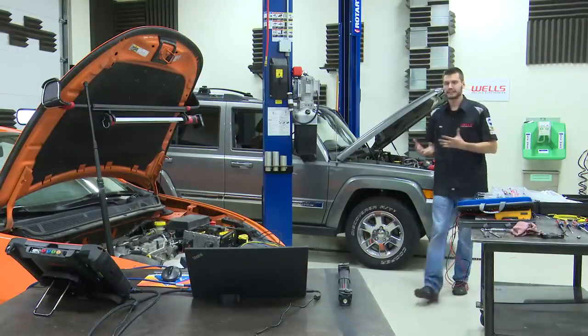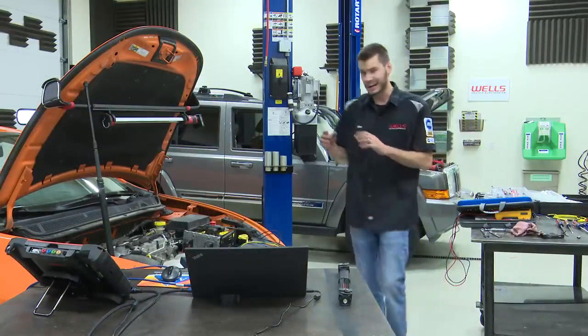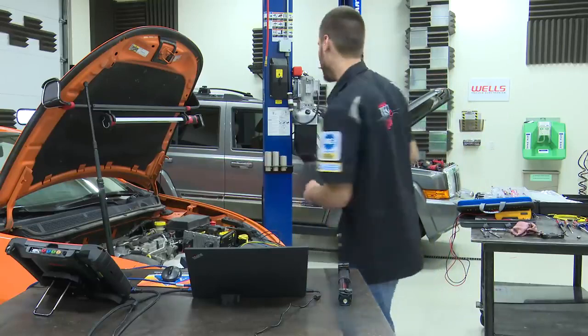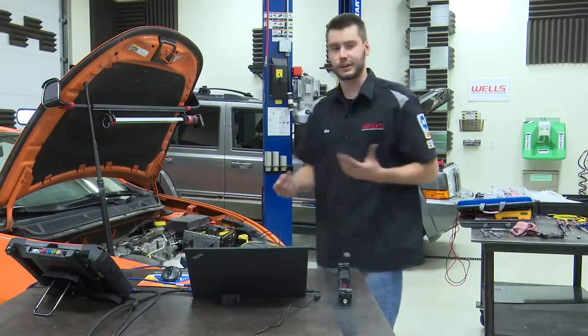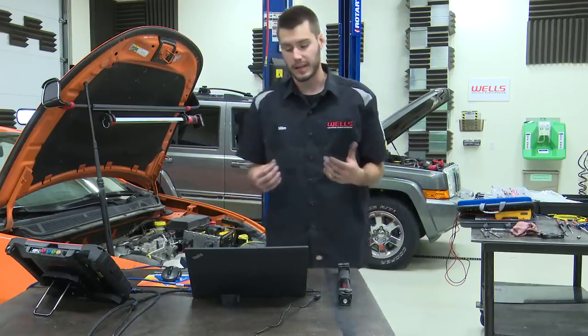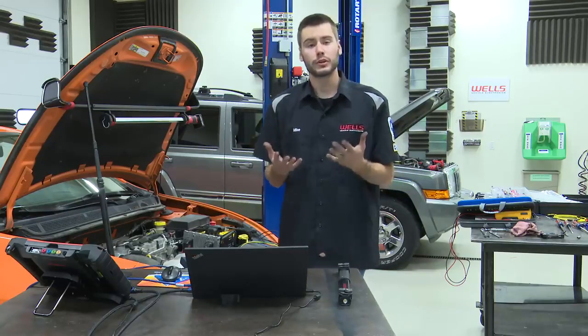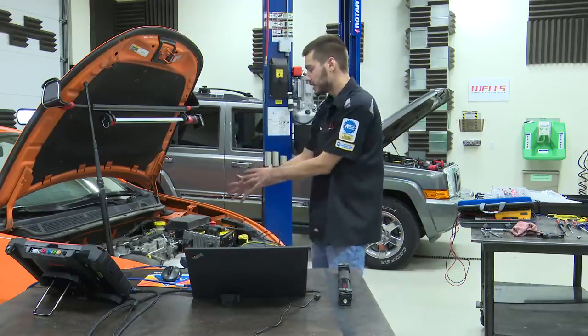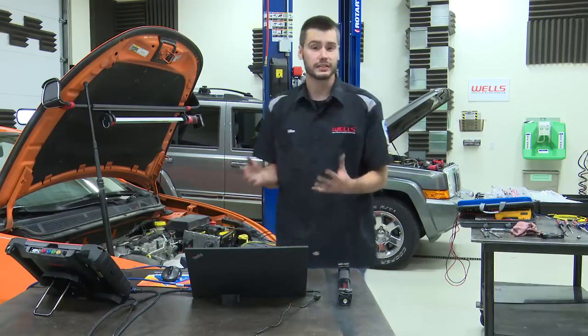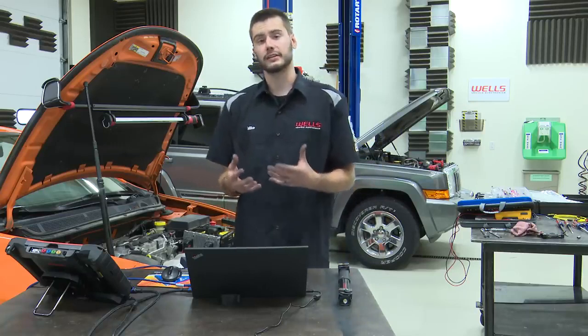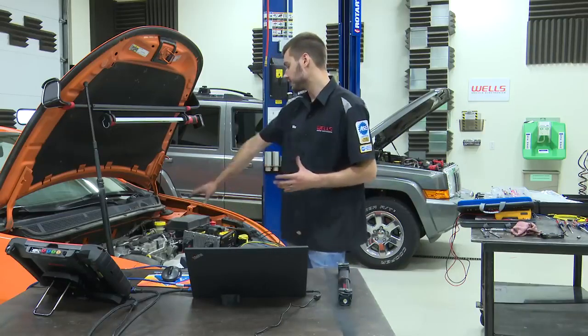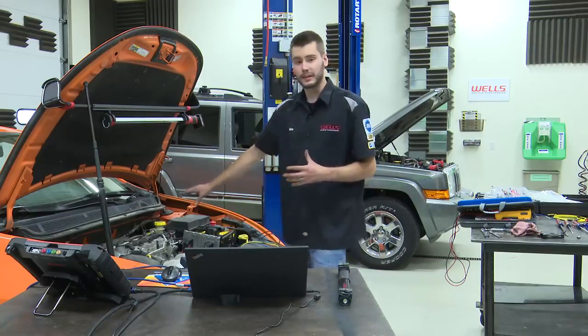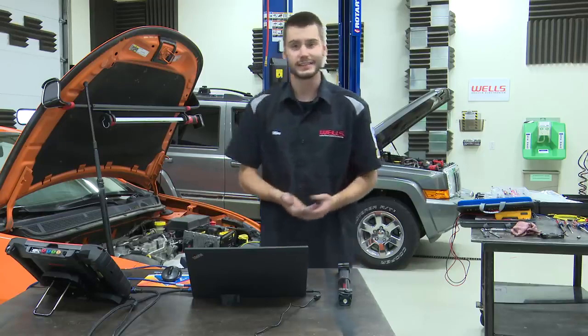Now I do want to note one thing, guys, here. When you're looking at scan tool data on newer cars, 2013, and older cars, and '07 is really not older, but it is still cable-driven throttle. Remember when you're looking at your throttle position PID that you're going to see different values. This car right here is going to vary throttle position because it is drive-by-wire. It no longer has an idle air control valve, so you'll see your throttle position varied by the computer when you do things like turn the AC on.